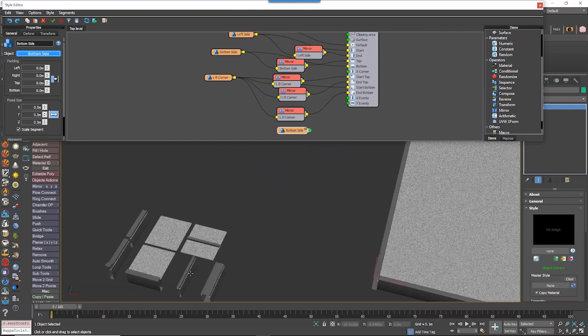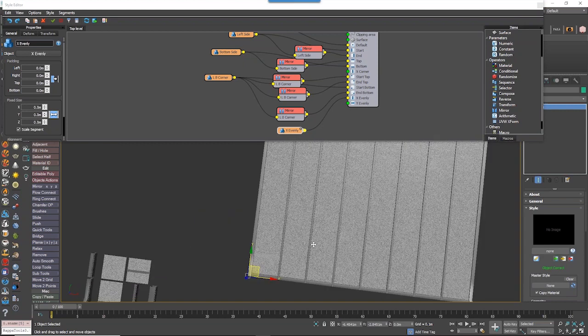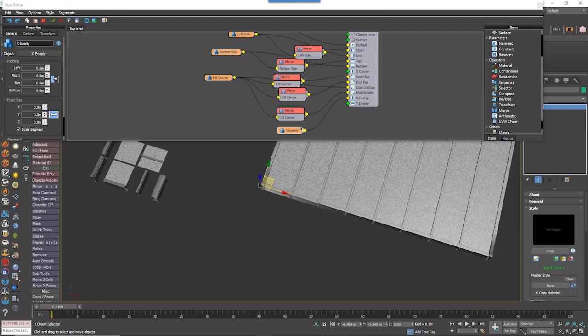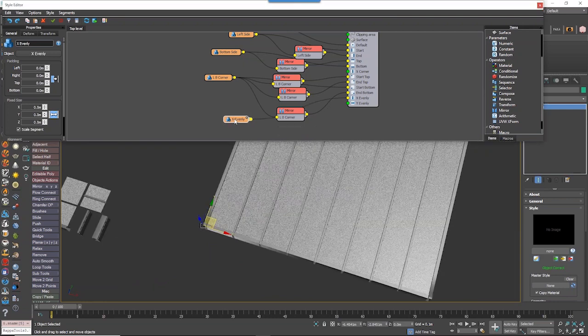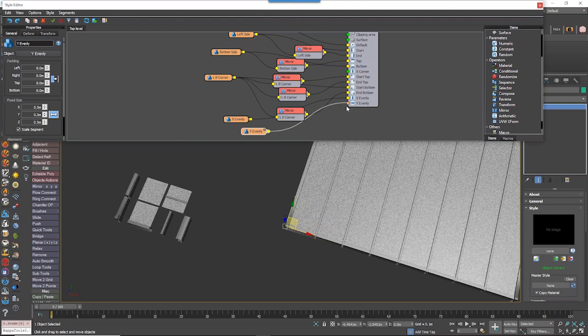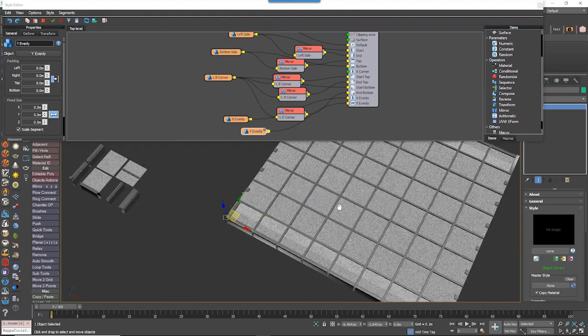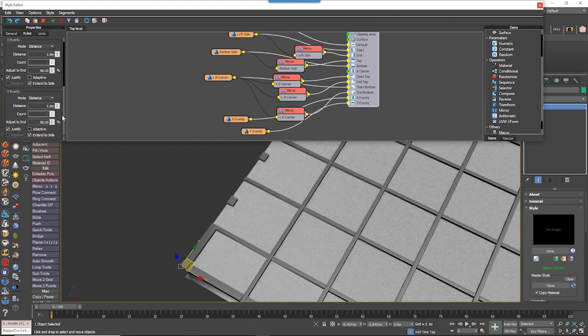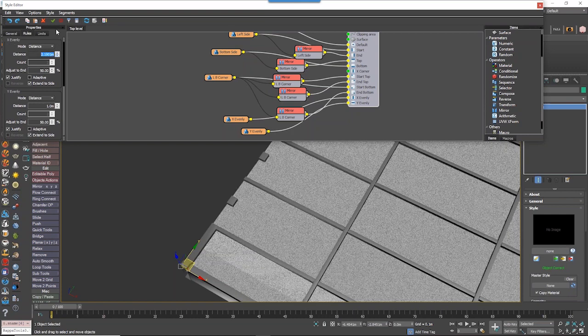So let me take this piece here, which is our X evenly, and wire it to the X evenly input. So that's all fine. And now we want Y evenly too. So I'll just copy this one more time, and wire it to the Y evenly input. Now, if you see on the side, first of all, let's adjust the distances. So the distances for these are in the same place, but now on the 2D array, you have two of them. You've got an X evenly and a Y evenly input, and you can adjust these sizes independently, obviously.